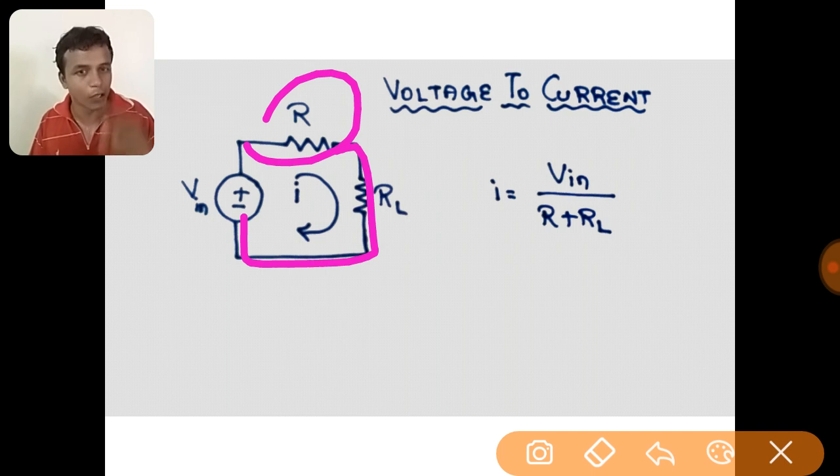So to transfer the signal measured by the sensor to the monitoring point, if we convert that voltage signal into a current signal and transmit, there won't be any loss. If the distance increases and we transmit the voltage signal, there is a chance for the voltage signal to get nullified. It may become zero before reaching the monitoring point.